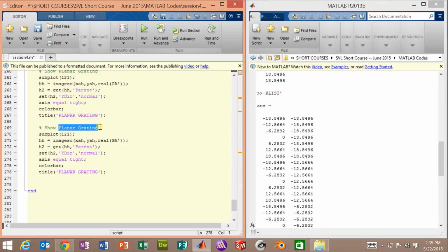And the last thing we want to do is show the overall lattice. And that is SVL. And the magnitude of the imaginary component of this will sort of come and go as we're adding different Fourier coefficients. So in general, it will have an imaginary part. So we'll just display the real part of it. And we'll call this the analog lattice. And then the last thing, we want to force MATLAB to update the graphics. To draw graphics. That's just drawnow.